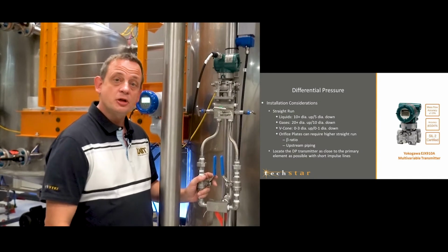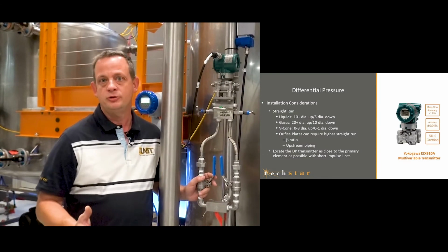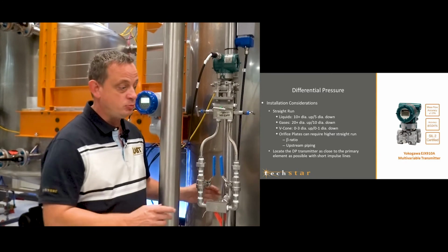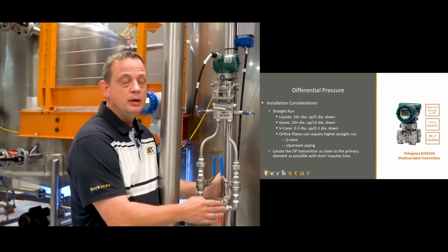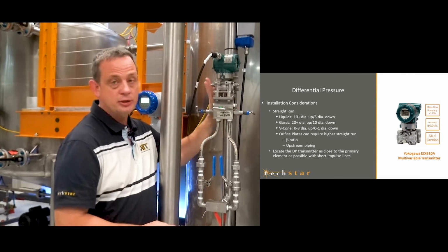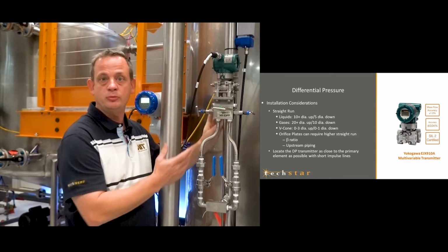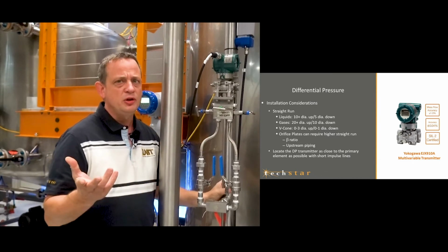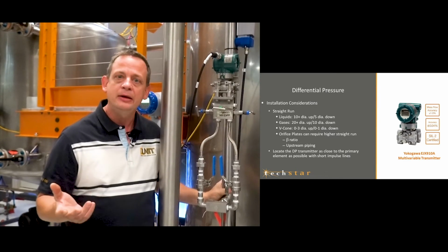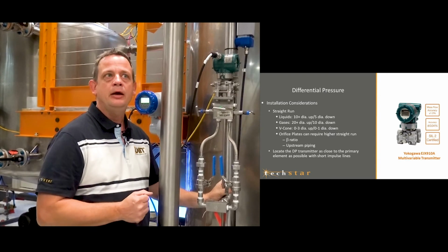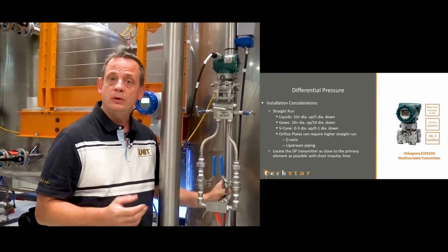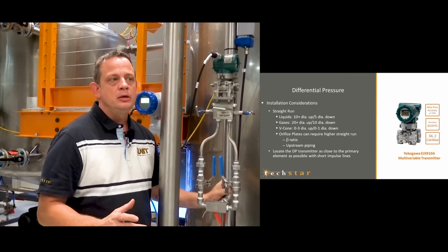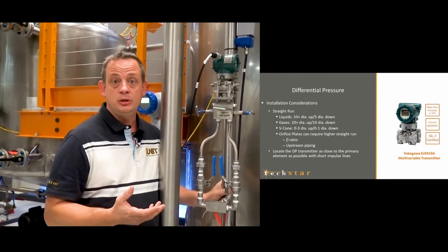All right, guys, so now let's talk about differential pressure flow. So there's several different styles of primary elements being the flow body, and then your secondary element is actually your transmitter itself, which will be your differential pressure transmitter. So I'm going to talk a little bit about your, let's say, orifice plate. If I had an orifice plate, I would need to have, for liquid flow, I want to maintain a full pipe like I do on these other ones. And vertical flow is usually preferred.